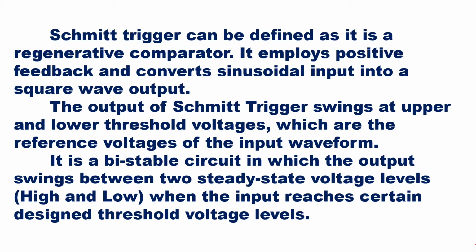So the Schmitt trigger can be defined as a regenerative comparator. It employs positive feedback and converts a sinusoidal input into a square wave output. That is obvious, as we'll see when we look at the circuit.